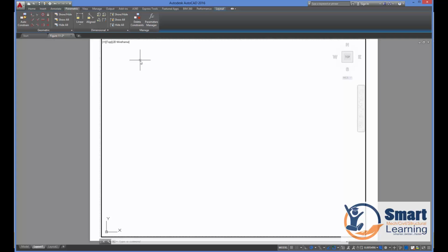To better explain, this is a very commonly used object. Here you can see the coincident, and here you can see this particular option known as smooth, another is parallel, and perpendicular we already saw, and this is collinear, which is very near to this one. So if you have object 1, object 2, and object 3, and you go for this particular option collinear, you can see this message, and I'm selecting the first object, and then you select the second object, and so on.